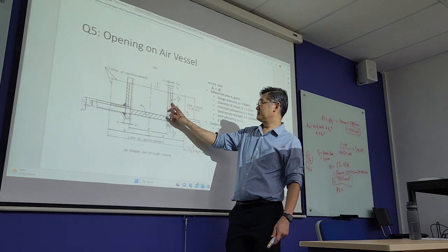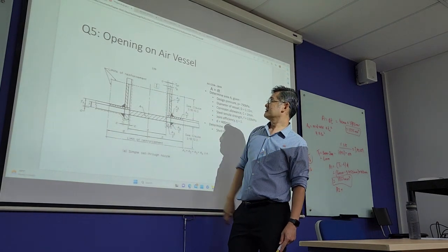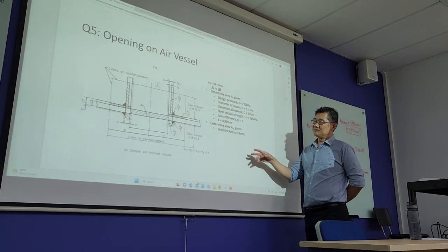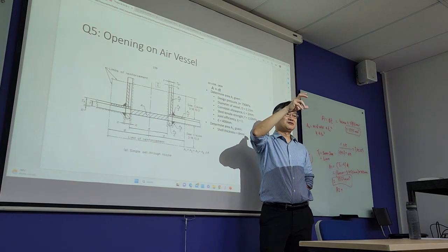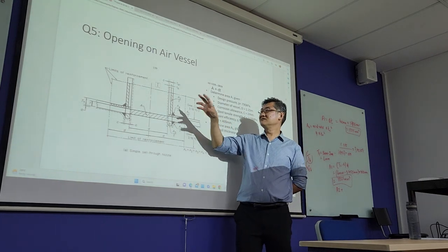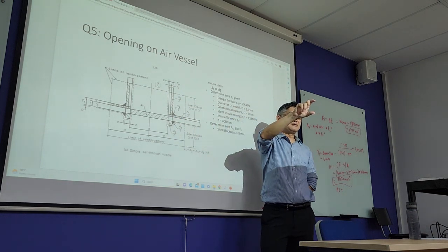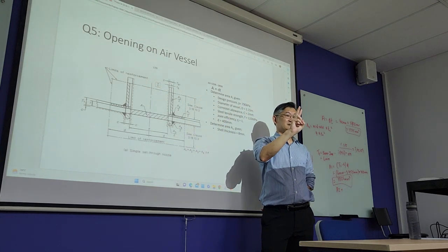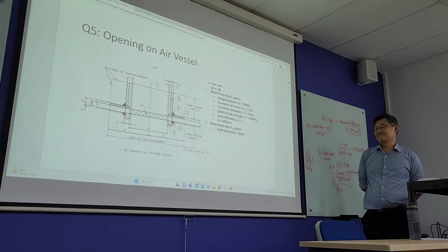So this part, we talk about the smaller tb, because some students are confused about why there is a capital T and also a smaller t. If you know how to differentiate them now, it is easy for you to do this question. The real thickness of the material and the thickness that can withstand pressure are different things.